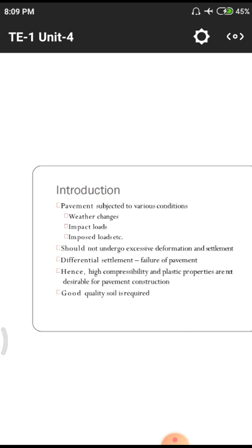Likewise we have different kinds of studies. After parking, we have traffic volume studies, where we have to ask each and every person involved in the particular road alignments so that we can collect the data. After the data collection is over, we have to sort that data into a number of parts, for which kind of area this pattern is suitable. Likewise we have different pavements, and in those pavements, what stresses are acting, what strains are acting, and what different factors we have, we need to know before going to design.